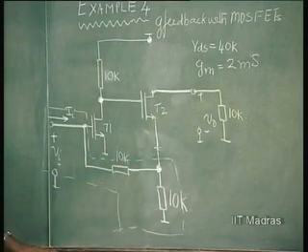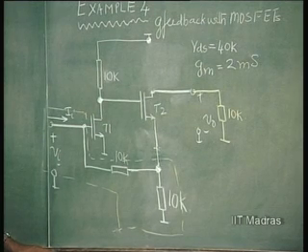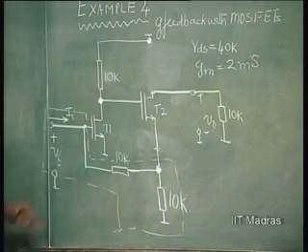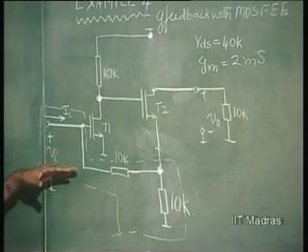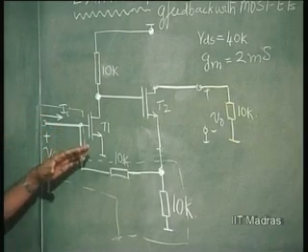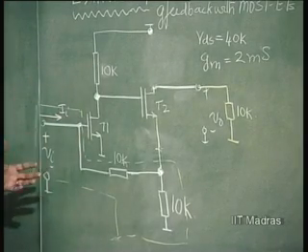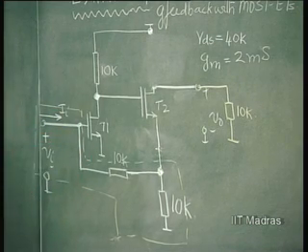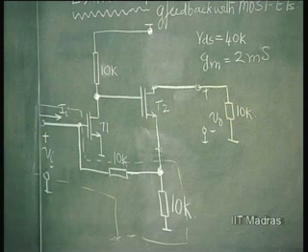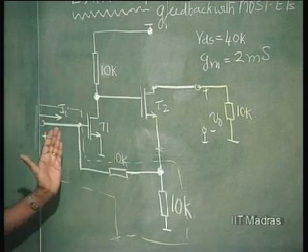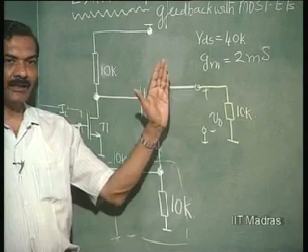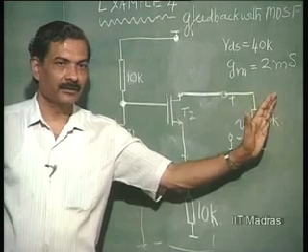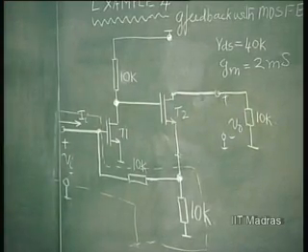So, this is an important point that you should note. Same thing should happen when we have things in series at the input. There should not be anything in shunt at the input, okay. Things should be in series at the input for H feedback. There also the amplifier should come in series with the feedback network, and bias networks and all should be considered with the source impedance, not with the amplifier. Likewise, in the case of series arrangement at the output, the load resistance should always be considered outside. This is something that you have to bear in mind.